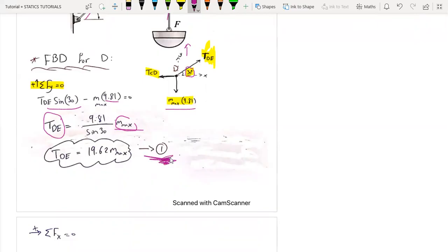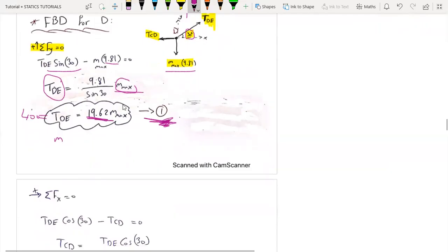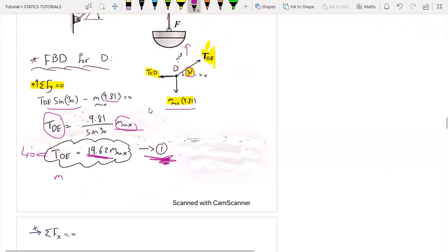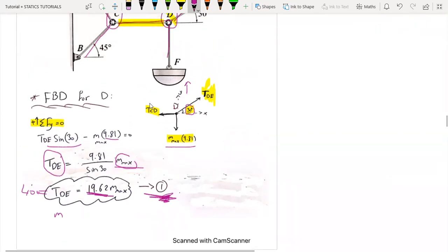So at the end, I will take the largest tension force and equate it to 400, because this tension force is the controlling one, and from it we will get the maximum mass allowable, which in fact will be the least value, not the maximum value. Here they mean the maximum mass allowable, so that we can avoid the failure of this system.